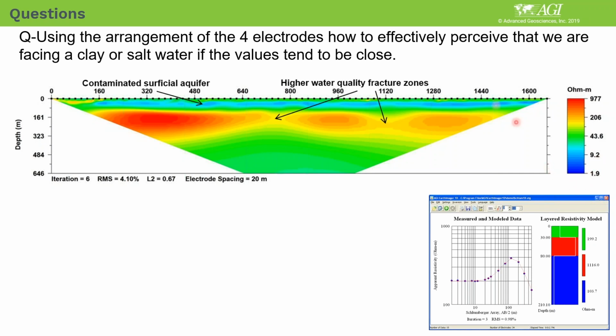So whatever I have seen on the top, these are all breakage, which is salty water. This is what we call a contaminated aquifer on the top. When they drill, they get salty water. If the client drills over here and gets salty water, and then comes up to very resistive material, there's no more water. They quit drilling if they don't have any geophysical study. If they drill over here, same thing: salty water, dry zone. Salty water, dry zone.